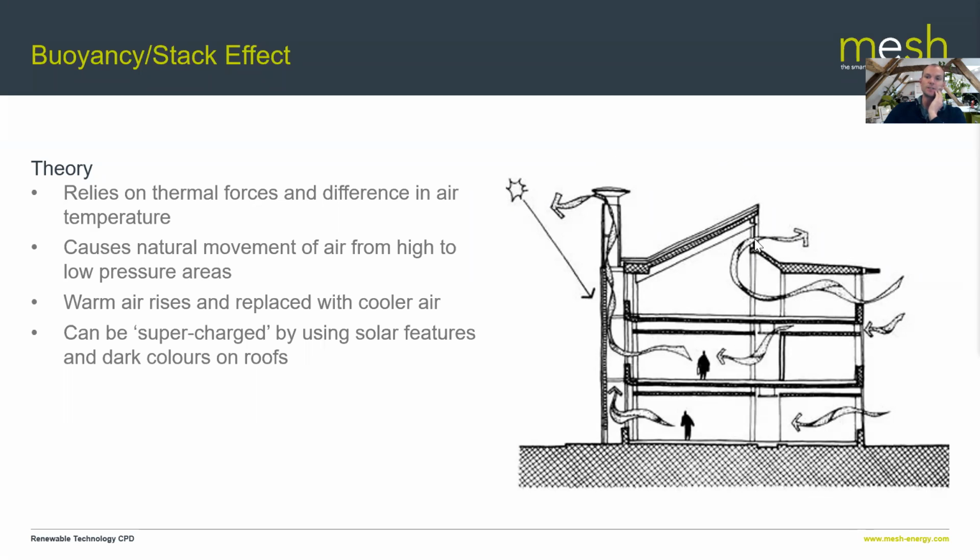and you can end up with more effective ventilation. It does require some proper design, but there are some pretty basic tools that are used around the globe, not just in the UK, to drive this buoyancy stack effect and really keep technology to a minimum, just using temperature differential and physical properties.